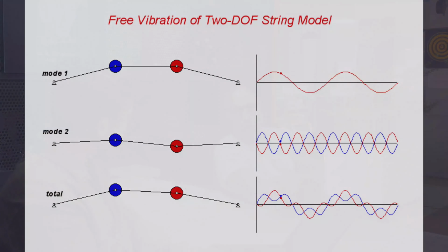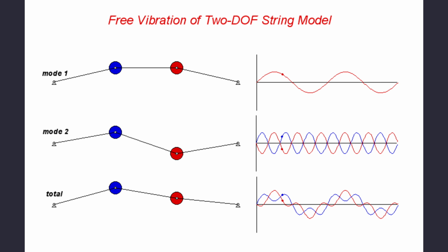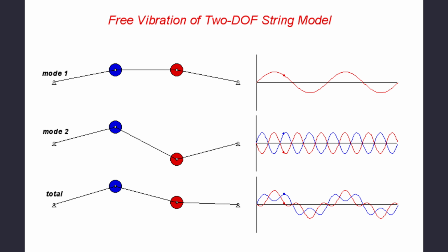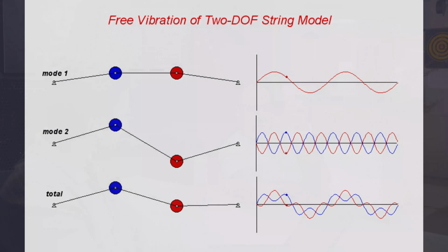But once the system is closer to its first flexible mode, which is typically called a critical speed in rotating equipment, and which we also call the natural frequency in static equipment, you see that the operating frequency is trying to coincide with the natural frequency of that rotor or the rotating part. Now you have a problem because your excitation frequency and your response frequency will add up, and this is going to disproportionately increase the vibration, depending on damping forces and other things in the system. This is an almost dangerous condition that we are talking of.